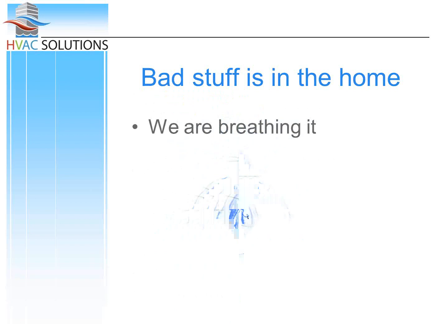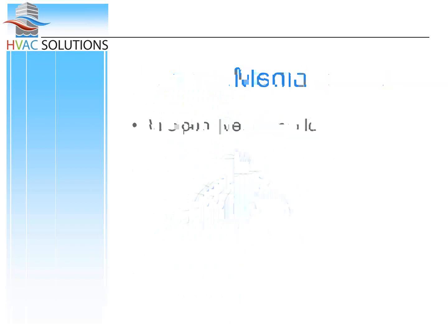And by big stuff, I usually mean pollen. But probably the number one thing that we forget about is that good media air cleaners do a great job at protecting the equipment. The homeowner just dropped thousands of dollars to put in new equipment, and you're going to use a 1-inch filter that barely catches anything, and a lot of that stuff gets caught on the coil, which leads to bacteria and other sorts of issues. So media filters do a great job at protecting the equipment.